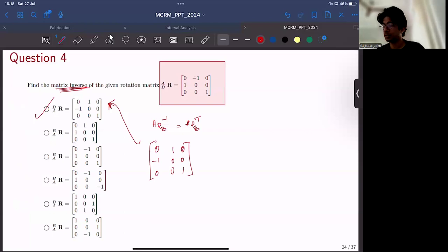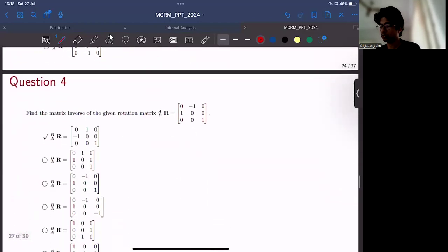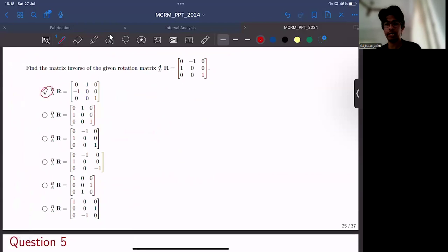Yes. Okay, so keep in mind that the orthonormal condition only exists for the 3 by 3 rotation matrix, and it's not the case for the 4 by 4 transformation matrix. It's only an attribute of the rotation matrix. So option A is indeed correct.